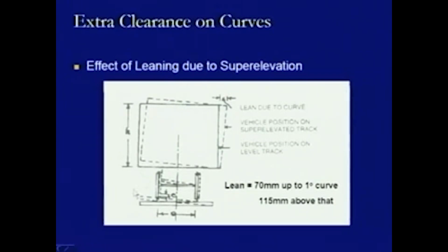Further, because this is a rigid condition and the size of the wheels remains the same, the distance maintained between the axle and the surface on which it is moving will also remain the same. So, this is also being tilted like this now. The axle has got tilted by some angle, which is defined by the value of E and the gauge being provided in between. So, E divided by G is tan theta, and this is how this angle can be computed as theta. Once this is happening, the new form of the bogie will be the one shown by the dotted line.